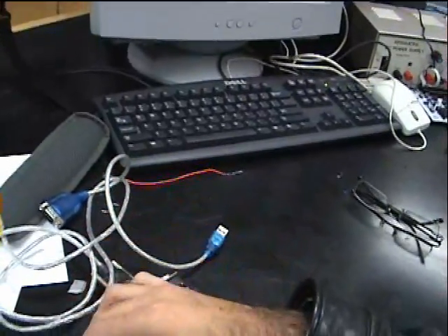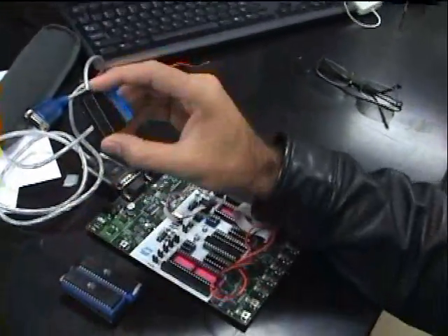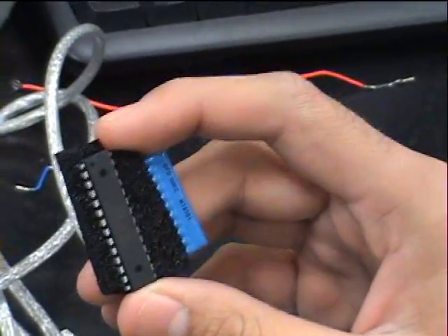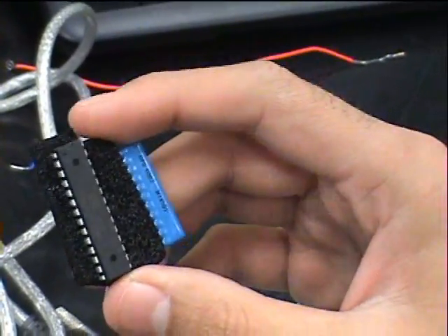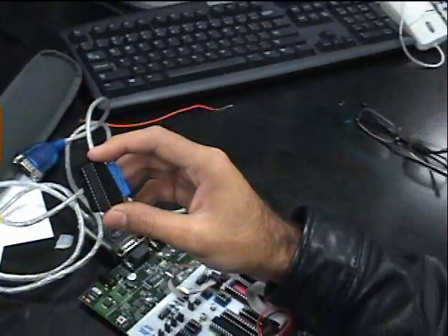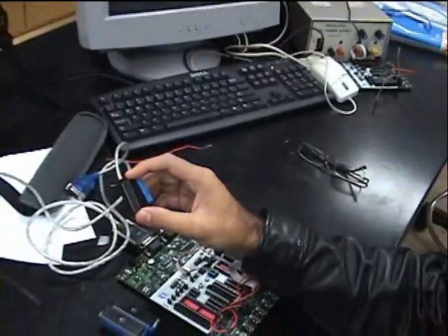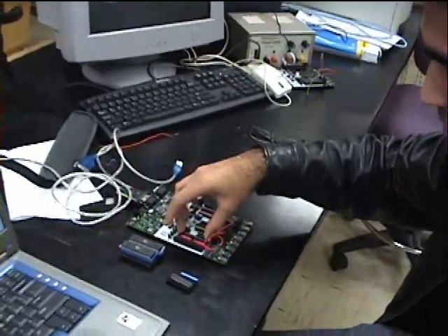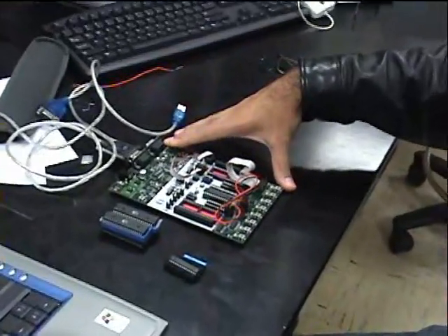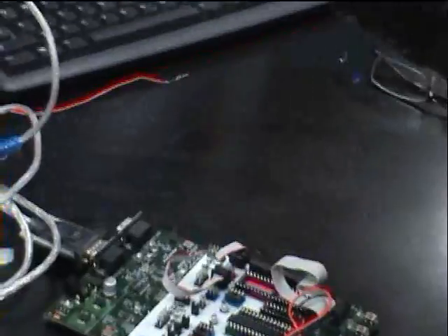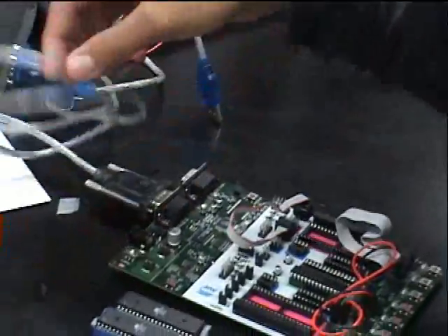So we went ahead and switched these with the smaller microcontrollers. The resources are just perfect for what we're doing. And there's still 2 of them, because one needs to do Bluetooth algorithms, GPS algorithms, and provide control signals. And the way we program is we just put the chip here on this programming board, STK 500, and we program through a serial port, and this is a USB to serial cable.